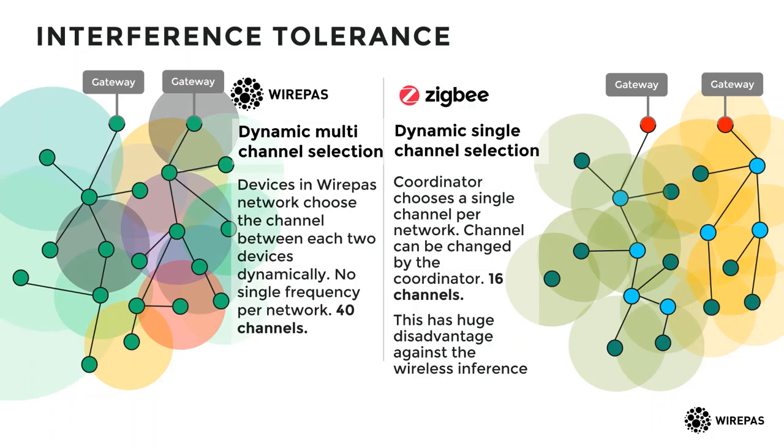Zigbee operates on a kind of similar topology in that it's a single channel, but it's one channel without any of that repetition, and there's really no active avoidance of Wi-Fi across the campus like Bluetooth has tried to do. And so effectively, when you set up your first node on your Zigbee network, it goes out and scans. It says, what's the freest channel in the place that this node is scanning, and then it builds the network on top of that channel.